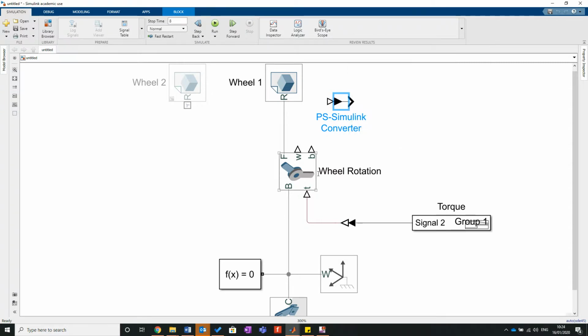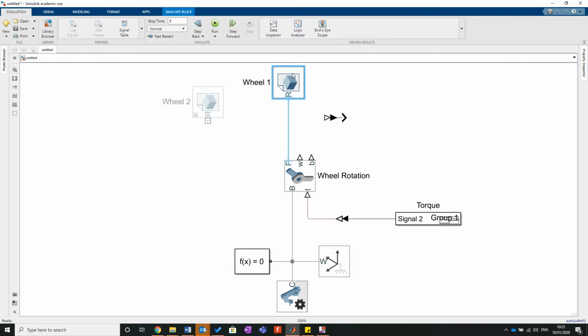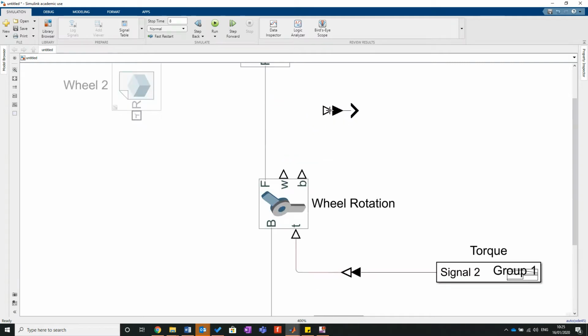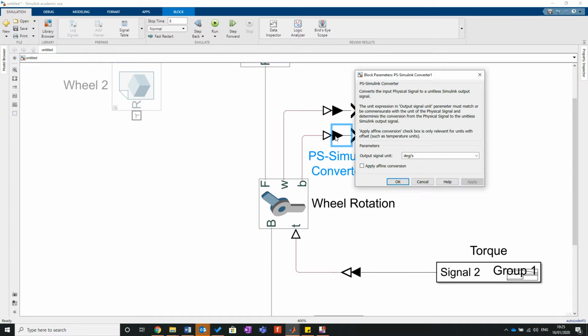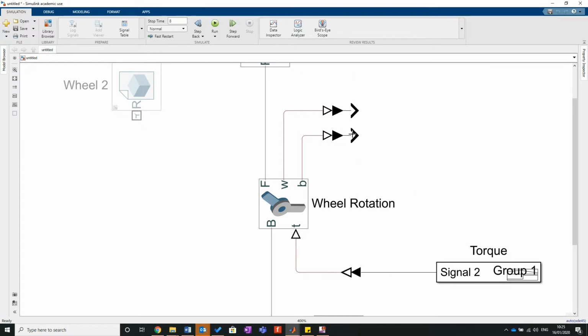Now if you were in class last week, you'll know that I always get these mixed up. Always. So I'm going to connect it up. I'm going to right click, drag one out, and connect it up to this. Now double click here, because I think this is the configuration that's correct. Basically, I'm attaching to velocity and acceleration. If you remember, earlier we turned it on in the revolute joint. And if I've got these configurations wrong, it'll say no, they don't work, so we just swap them round. Knowing me, it's quite possible.